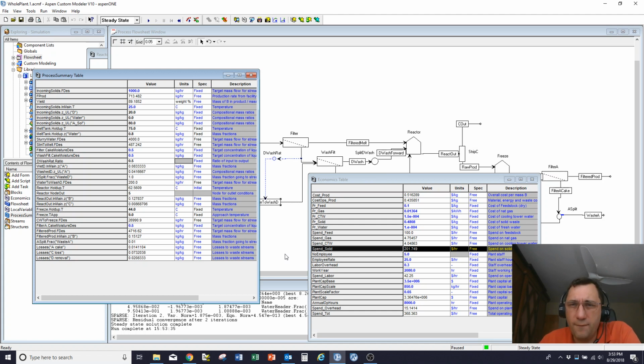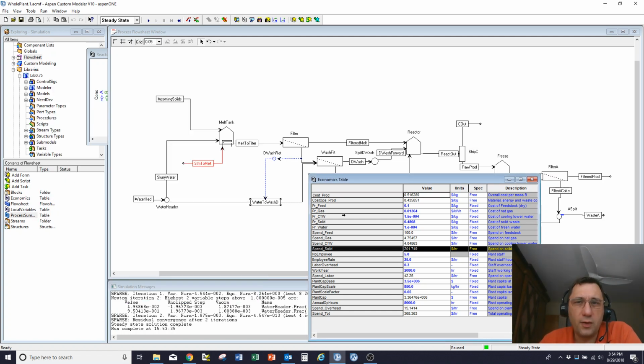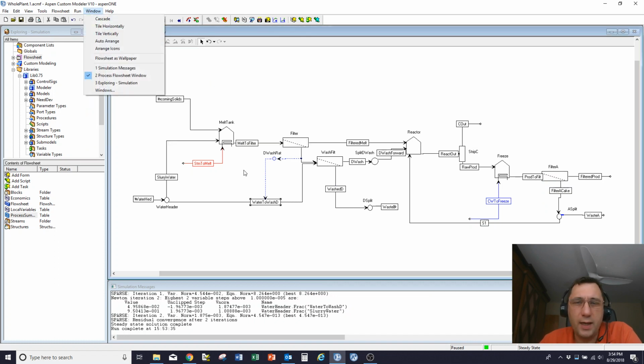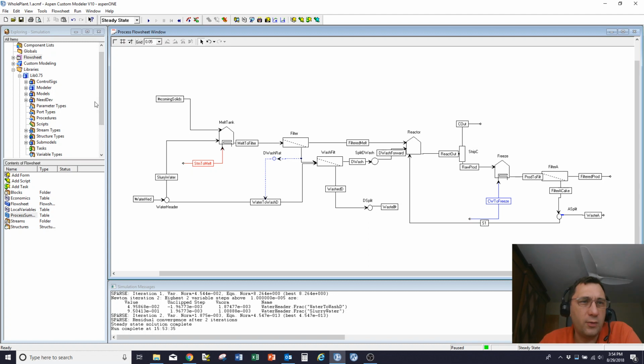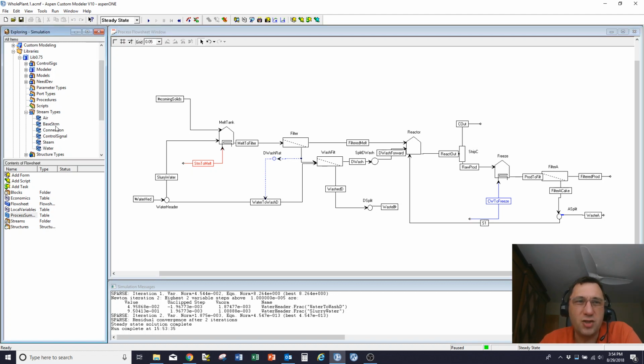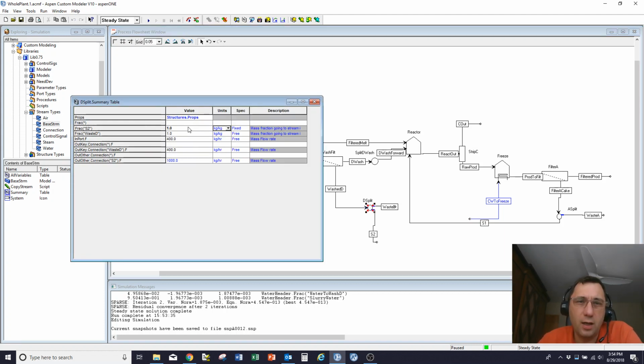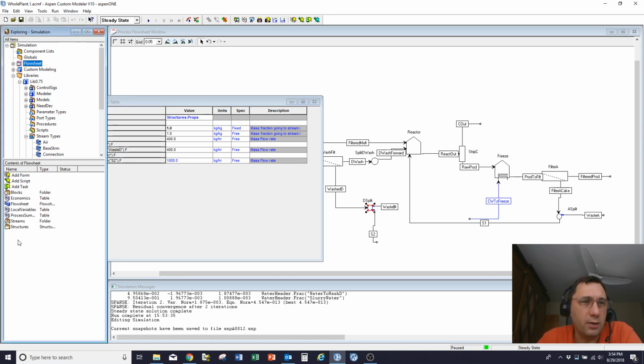Okay, so I've worked through various options there in terms of how to change the flow sheet. The big cost remains the solids disposal. So let's magically assume I can come up with a different way of disposing of those solids where I essentially just give it to somebody. So rather than sending it to landfill, I find somebody who's interested in having those D solids, and I'm going to divert all of the solids to that new user to reduce the material going to landfill.